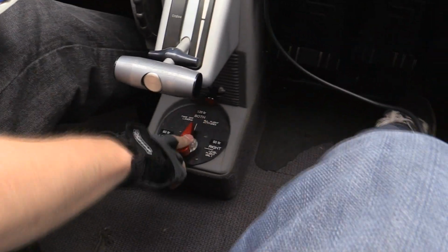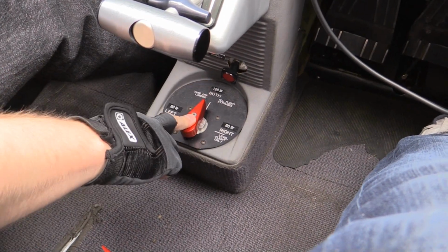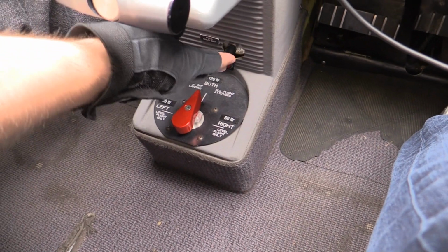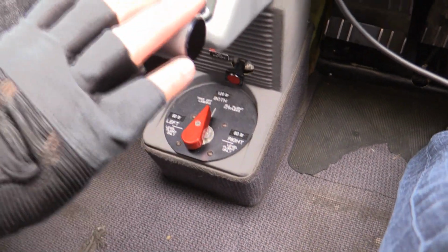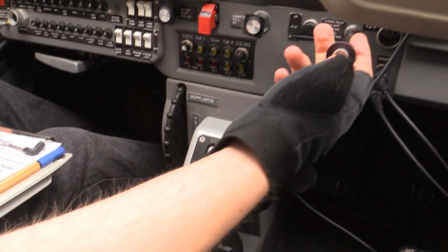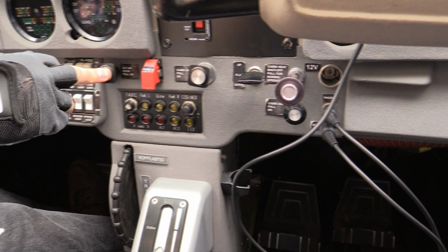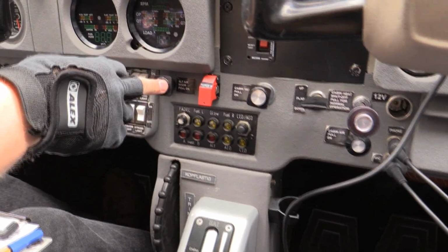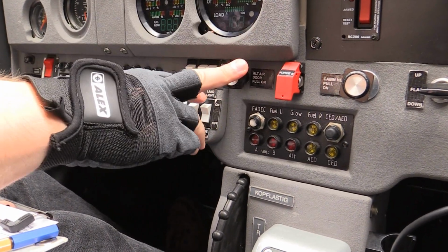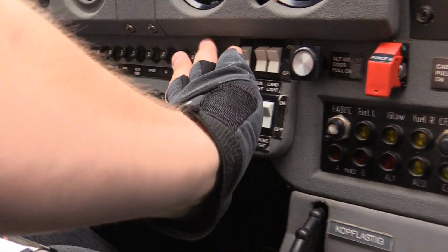First we want to see that the fuel selector is on both tanks. So you can either select left, right or both. This should be at both. The fuel shutoff or fuel cutoff is in, so we got fuel supply to the engine. Our power lever is on idle and it's freely movable. Then the shutoff cabin heat should be fully pulled out for normal operation. The alternate air door should be closed. This is for this diesel injection engine. You have to have an alternate air source in case your air filter is going to ice up. So this should be shut. All switches here should be off. The avionics master is off and all the circuit breakers are in.